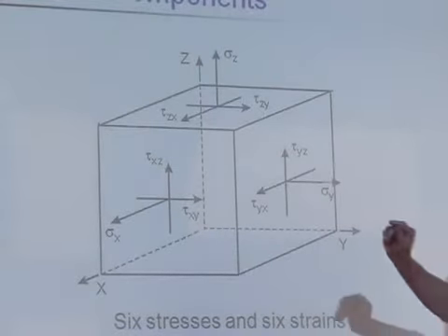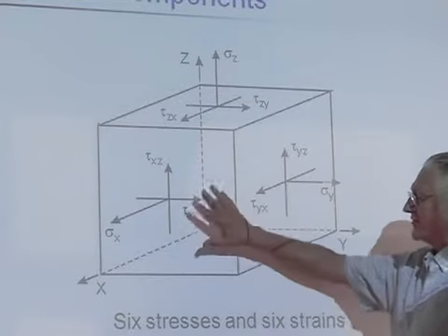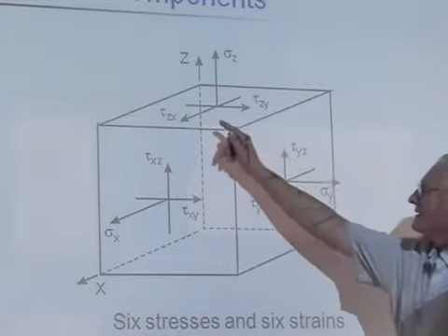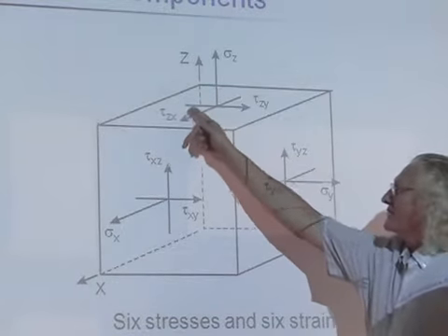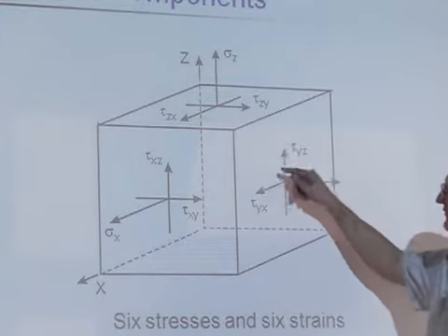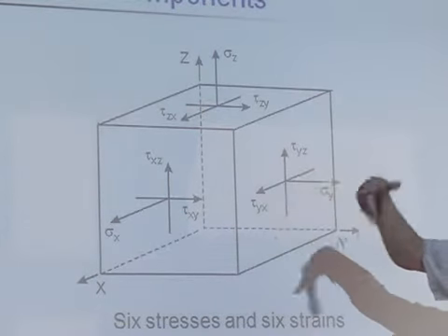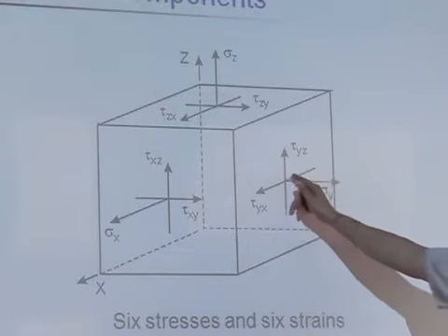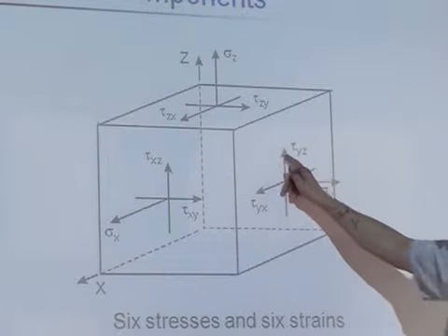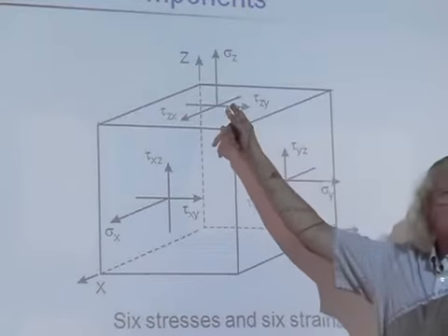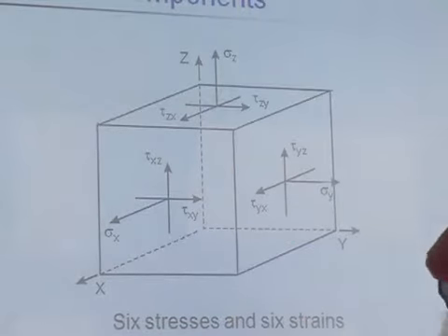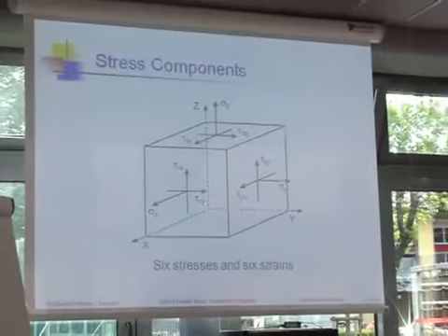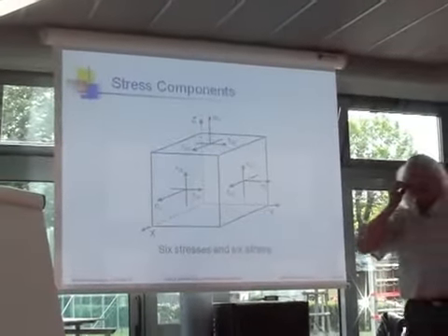in the picture, then you have a shear stress that acts on each face of the cube in 2 different directions. And the mathematicians like to separate this shear stress and this shear stress. That makes it nice to work in tensors. The engineers realize for this cube to be in equilibrium, these 2 shear stresses, this one and this one, must be the same, or else the cube spins around in space. And so engineers only like to work with 6 dimensions. And the math people like to work in 9.